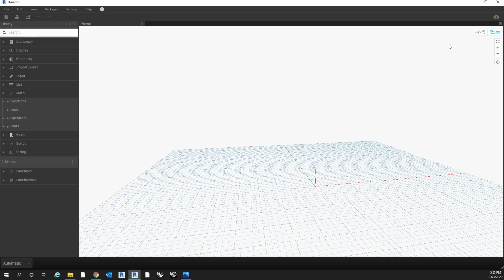The other is a workspace that mimics the three-dimensional field of whatever you're creating. Now that field ties back to Revit. If you go to the top right, there's two different buttons. One visualizes a series of nodes connected, which is your script workspace, and this one is more of your 3D objects. That's your 3D space.